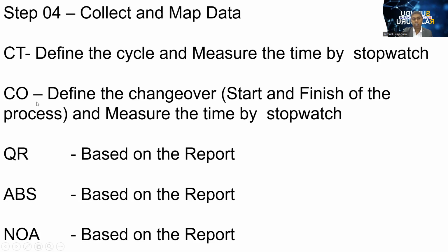So for changeover data also, define the changeover, meaning the start and finishing point, then measure through the stopwatch. QR, absenteeism, number of associates, all that data you can take from the report. So some data you have to collect physically, by being in the production operation flow and using the stopwatch, through your own study. Then some data you can take from the past report.